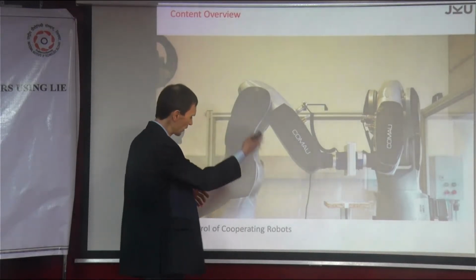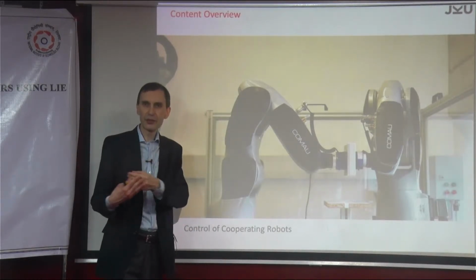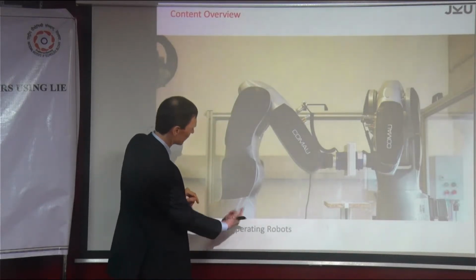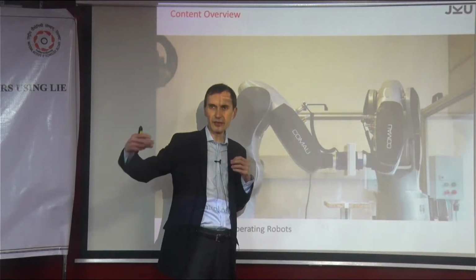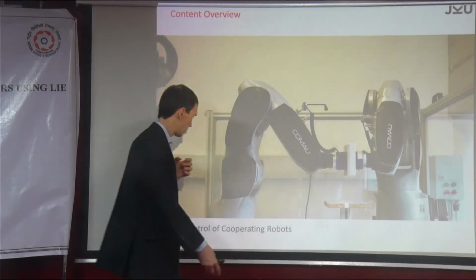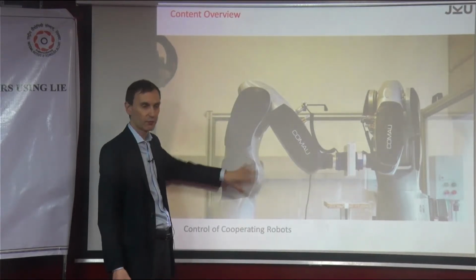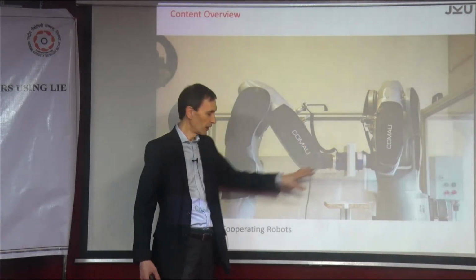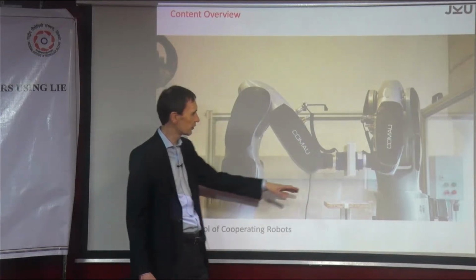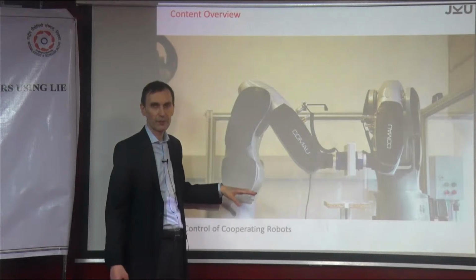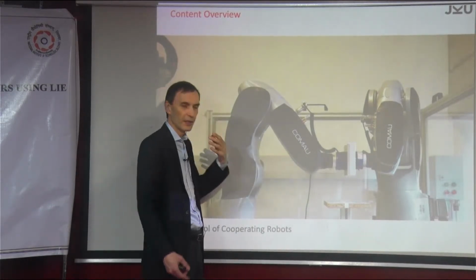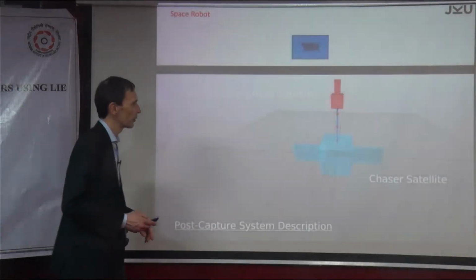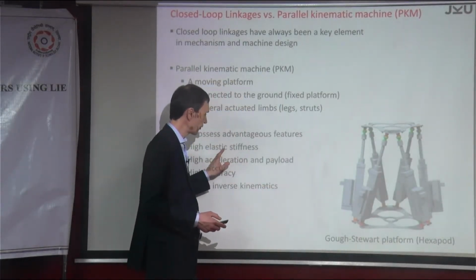And what happens in this standard robotic arm is that you are kind of adding up the stiffnesses, right? You have the stiffness in this gear, then there's one here, and one here, and so on. And you add them all up in a long chain, and all together this gives you the total stiffness. And also, look at this motor here. There's one motor that is moving the system, and it's actually moving all the motors that come after this motor in the chain, right? And the same is here. So this motor is not directly influencing the end effector motion, but it has to move the whole system for no purpose, because initially I don't want to move the robot, I want to move the end effector, right? So what I'm saying is, this was actually one of the arguments for having these PKMs, because the stiffness and the payload is increased.